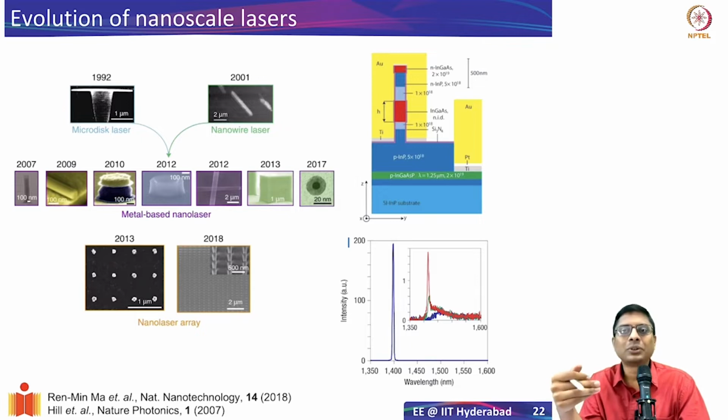So if you want to have a good working laser, we need to make sure that the Schottky barriers are avoided, or at least minimize the junction width, the Schottky barrier width, so that tunneling happens and we can overcome that. So that's why whenever you contact with metal, they try to have large doping so that the barrier is very, very small and narrow, and you can actually overcome that. And also the entire structure has to be very, very carefully designed so that you minimize the resistance for both electrons and holes. So a lot of careful design is done to do this.